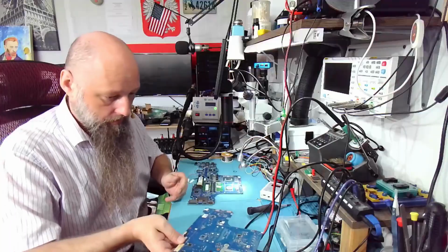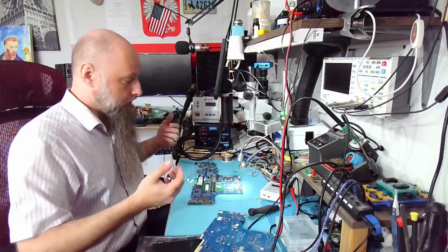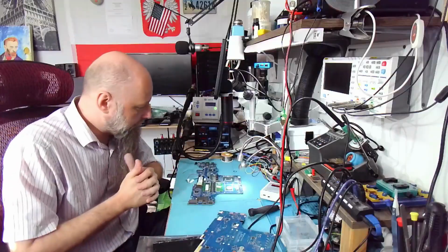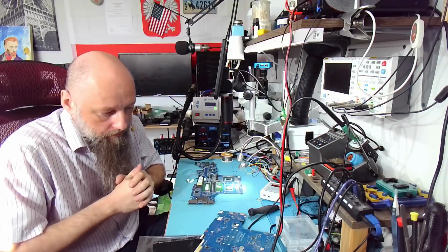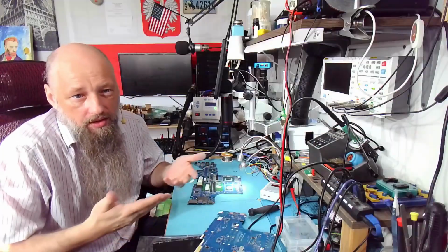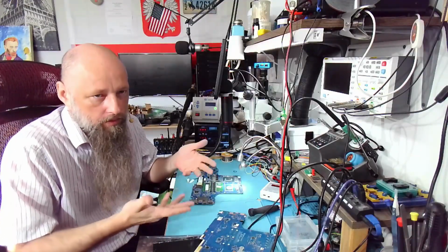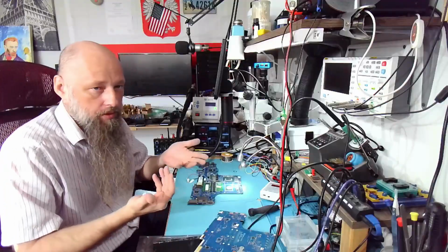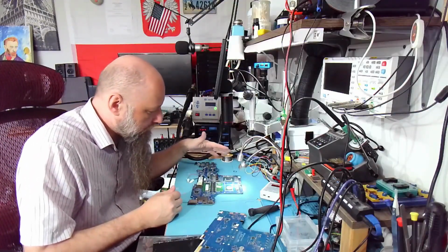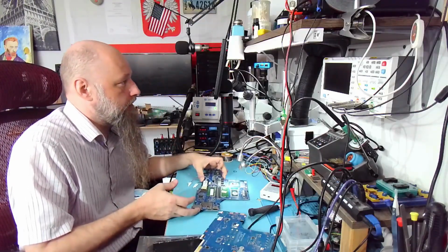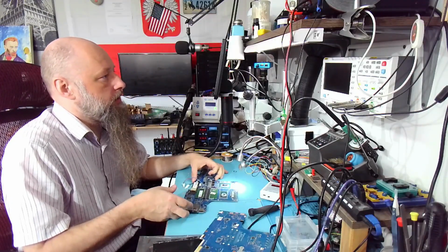A lot of work went into that, I bet, and a lot of frustration, and the board doesn't seem to work. Now the GPU core could be faulty. Resistance is just one measurement. Even if the resistance shows up good, it doesn't mean the GPU actually works. I don't see any damage around it. I don't see any missing components. I don't see anything that would explain this behavior.